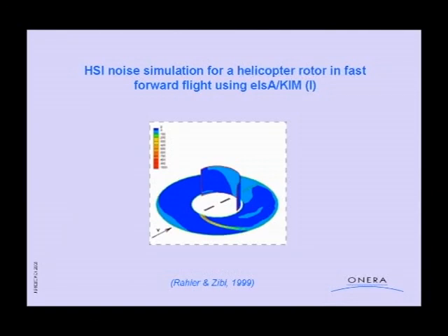And the control surface is this half of the cylinder here. And we have used about 4,000 observer locations for this unsteady calculation. And we need less than 1 hour of computing time on a PC.